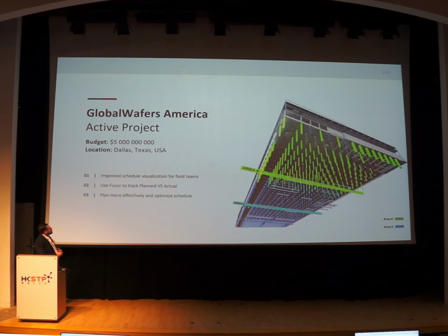And so we use Fuser on this project. It helped us improve schedule visualization for field teams. We use Fuser to track plan versus actual. Fuser has a great tool: if you import the actual dates in your construction schedule, it'll compare the plan versus actual. And it allowed us to plan more effectively and optimize the schedule.